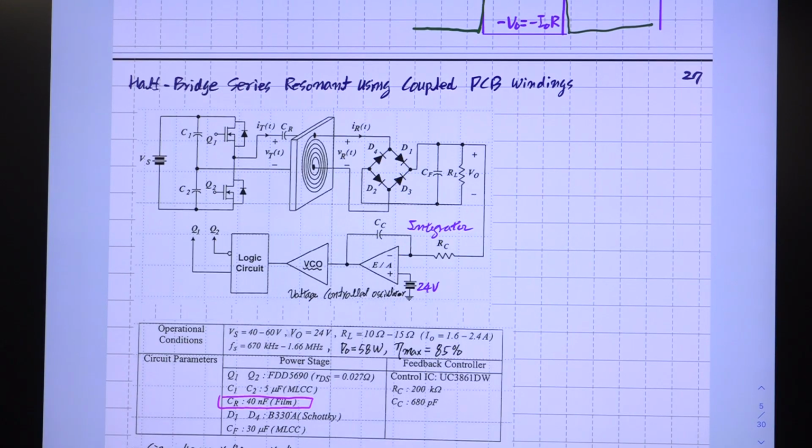But this can be improved. Right? Actually, the later part of this lecture will focus on the designing of this one. Okay, maybe this is the worst selection. I'm saying always, this integrator is the worst compensation. It only provides DC regulation, and it hurts the stability margin and other closed loop performance badly.